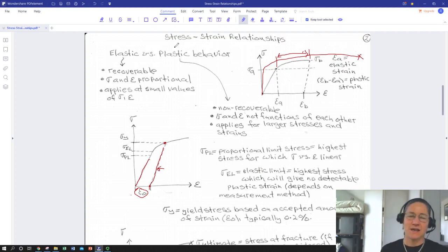Okay. We will not be dealing with plastic behavior. We will deal with the onset of yield and how to predict when we are likely to get yield, based on our elastic properties and a yield criterion that's based on test data like this. But we can say some things about plastic behavior to keep in mind for design. It's non-recoverable, great for forming, bad for in-service applications.